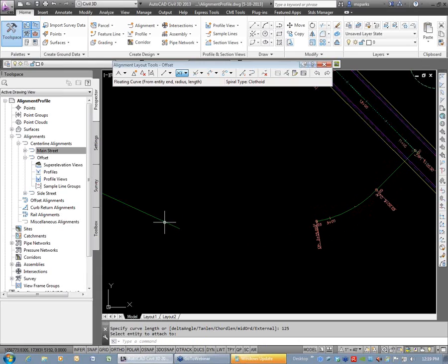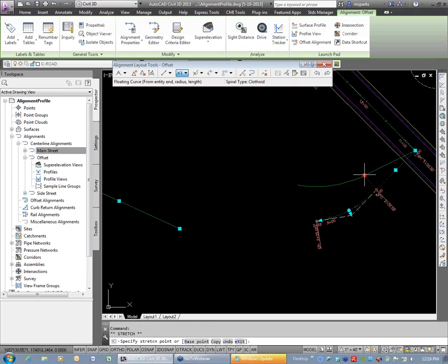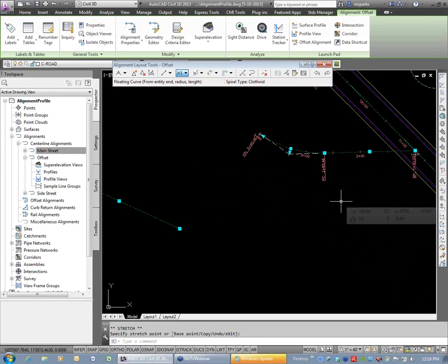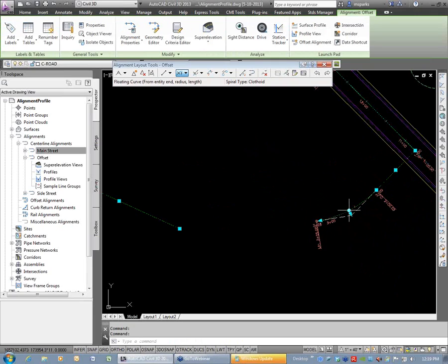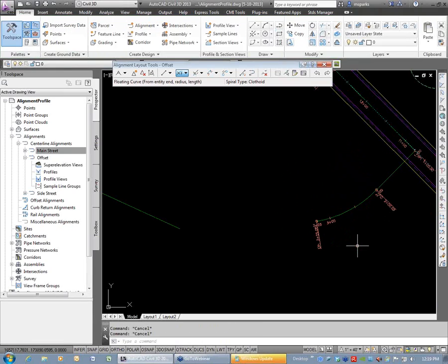This is still not being labeled. So then I want to put a 100-foot tangent here, and then I'm going to put a curve between these 2 objects. Okay. But the reason why this is attached, right, if I come over to here and I move this around, you'll notice here that that's now linked. Wherever that goes, that curve will be tangent from that point. Okay. So this is called the constraint-based design. So same thing, if I grab the curve, it's automatically always going to be tangent. So I can edit it that way if need be.